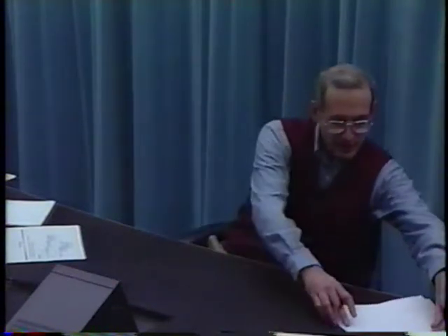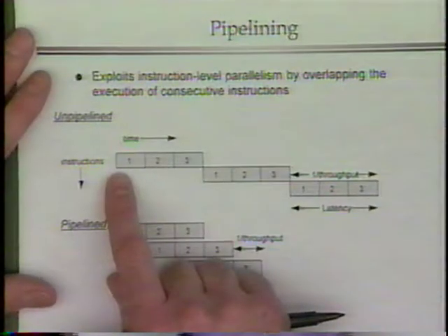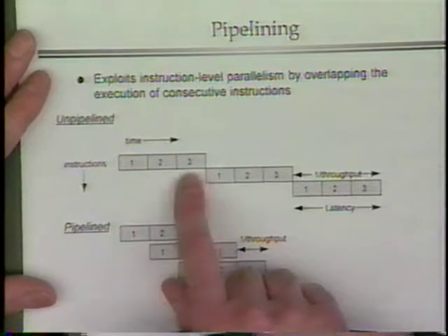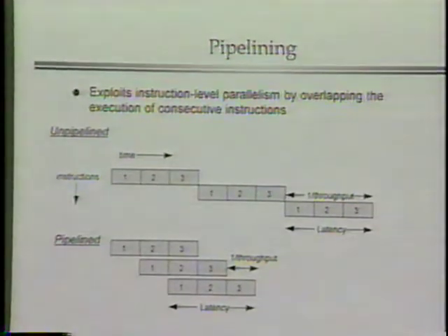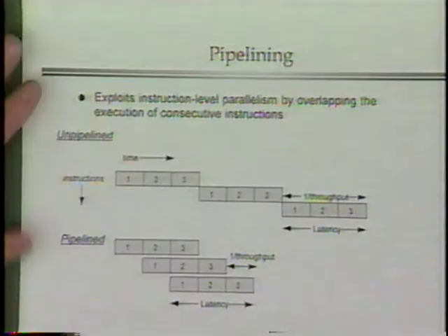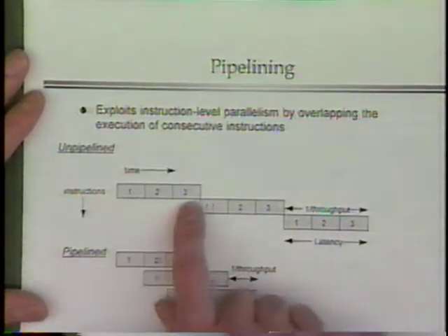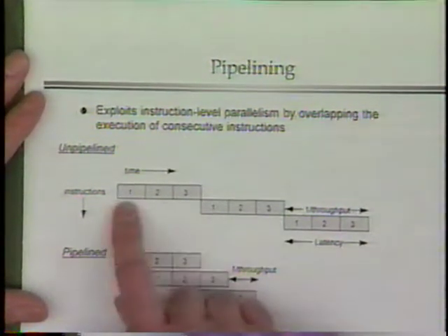Okay, that's DLX. Let's look at what pipelining is and how we might apply it to a DLX machine. Notice that although I described that machine as a single cycle machine where you feed all the results in at the top and something happens at the end, you can consider breaking that operation up into multiple steps and break it up any way you like.